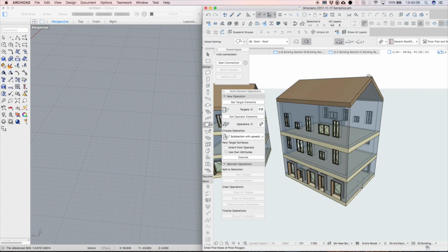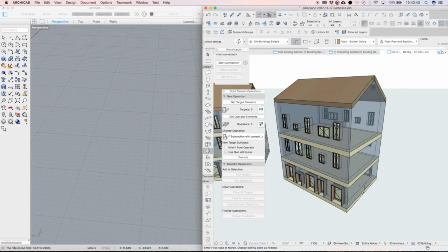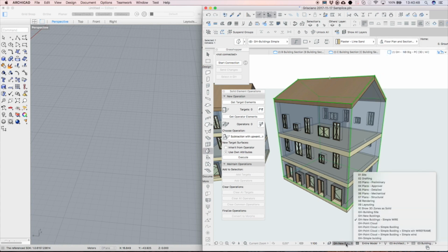Please note that the conceptual Morph shapes and the real wall, slab, roof, window, and door elements are associated with each other. This means that if we modify the shape of the Morph or reposition the planar objects that indicate openings, then the ARCHICAD model will update instantly and automatically. There is no manual process necessary. Let's demonstrate how this works.